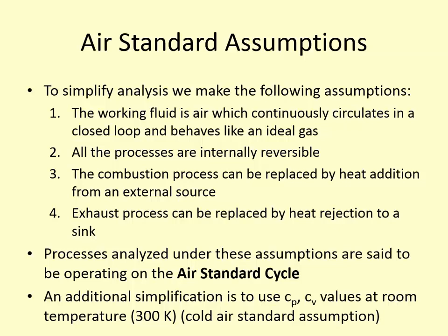So if this one is a greater work-producing device using these air standard assumptions, cold air standard assumptions, then it still will be when we actually have fuel and exhaust gases involved. The mechanisms that make it good don't necessarily rely on the temperature of the fuel.